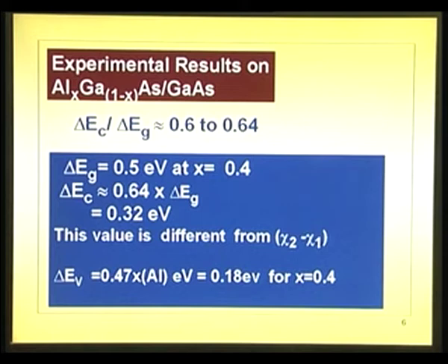Okay. And now, a few things I want to bring out, because we have drawn certain diagrams in a certain way. So, we will take a look at those diagrams and also see this. Here delta Eg, now we are talking of the gallium arsenide aluminum arsenide system. Delta Eg is the difference in the band gap. Now, how much delta Eg is depends upon x.